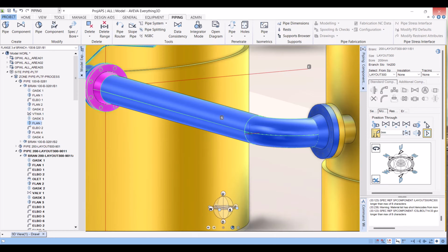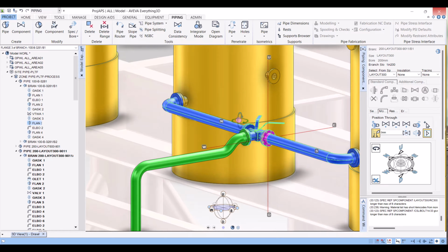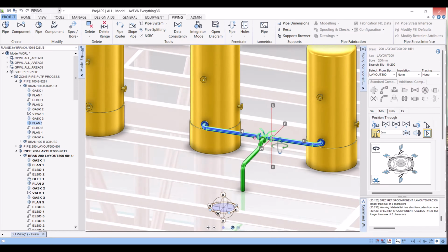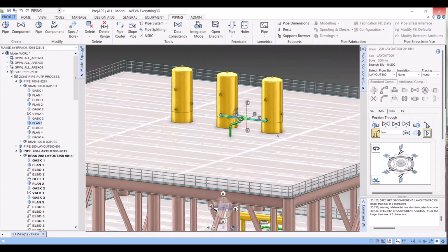You give this 1 in 100 or 200 from your pipe, and then here you give from this point to this point. You have to give slope two ways here in this type of pipe routing. Try this one.